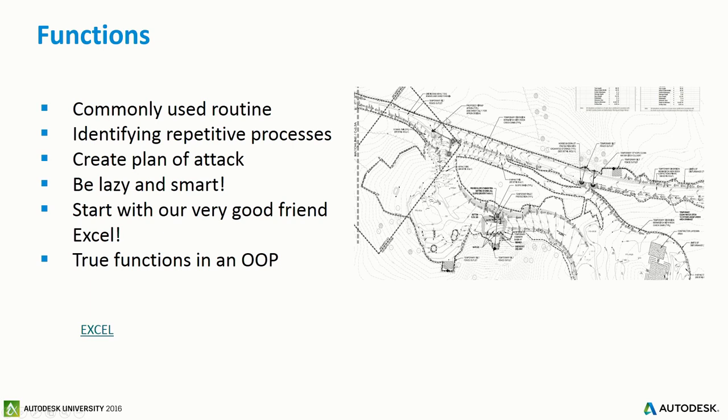Okay, for a little background, this is an erosion control plan. I know everybody in here is not land development people, but basically this project had a lot of linear roads and greenways that can usually be treated by silt fence, and we had a regulatory agency that was kind of a stickler and made us size these temporary storage areas everywhere we had an inlet protection or silt fence outlet.